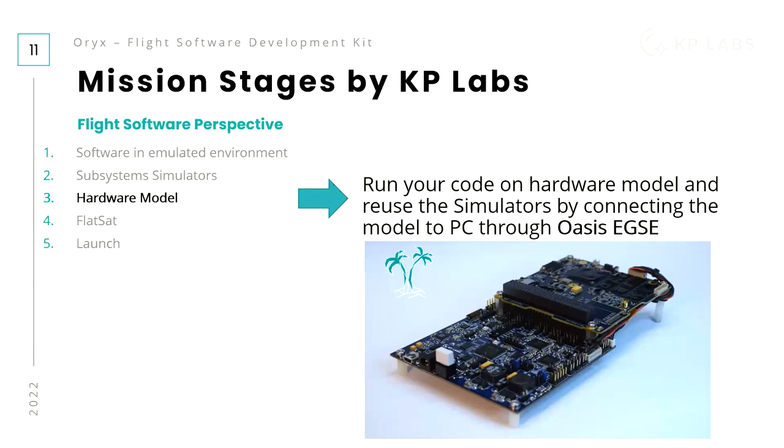It captures the I2C, CAN, GPIO, UART, SPI, and in this case it serves as a slave. So if the OBC wants to read something, for example from temperature sensors, it will create an I2C transaction that will be captured by the Oasis. The transaction will be sent to the same simulator we have already written for QEMU. The answer will be generated, translated back to an I2C response, and sent to the OBC. So from the OBC perspective, it looks like it's talking to real hardware.